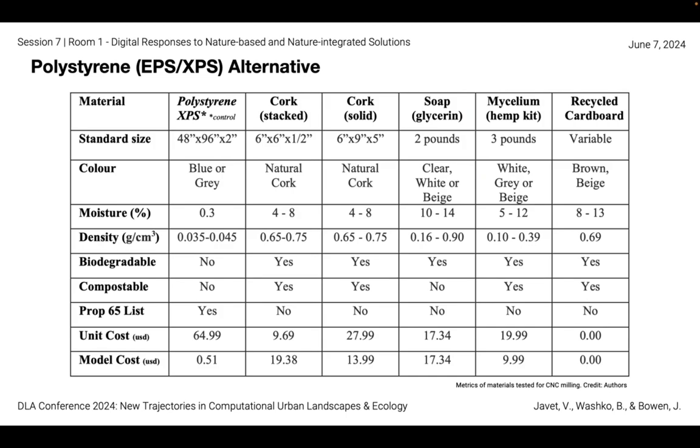Each selected material contains a unique set of metrics in terms of their color, moisture, density, toxicity, cost, biodegradability, and/or compostability. Of particular note are the metrics of moisture and density in terms of the material's implications for CNC tooling settings. A lack of guiding rules for users introduces uncertainty about process outcomes and really prevents end users from relying on preset tooling selection.